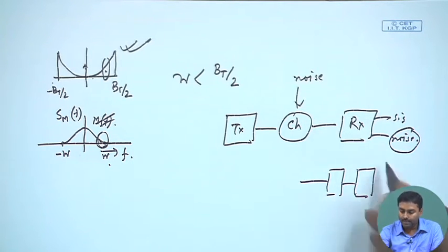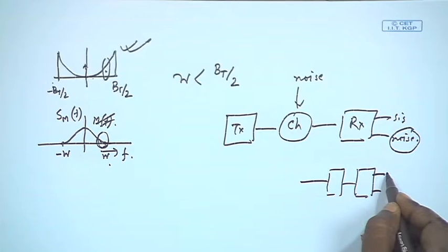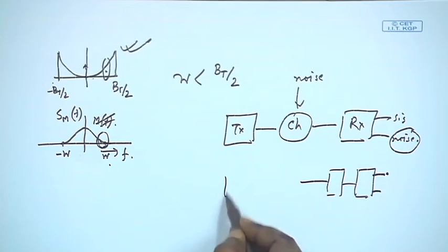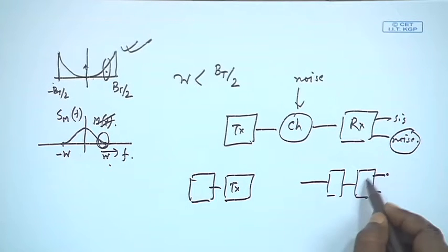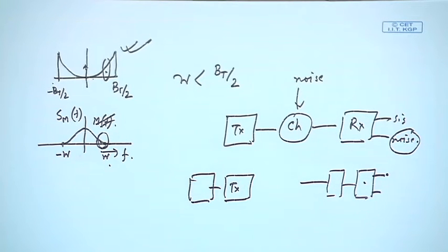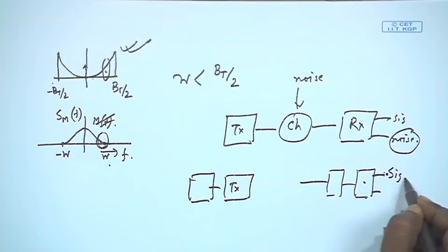So, at the output I will see the same signal, because it was boosted at the transmitter. Before transmission I have this boosting, and here it is the reverse operation. So, I will get the same signal, but this noise power will be much more reduced. This is a technique which has been employed in FM, which helps in combating noise even better.